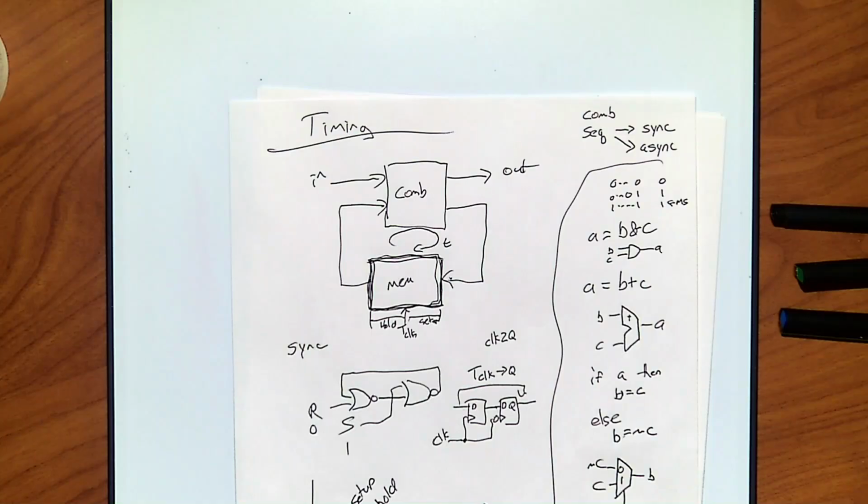We're running about 11 and some change inches. There's a little bit less than a foot in a nanosecond. We're dealing with a third of a nanosecond. So how far does light travel for your typical desktop machine? Less than 4 inches.